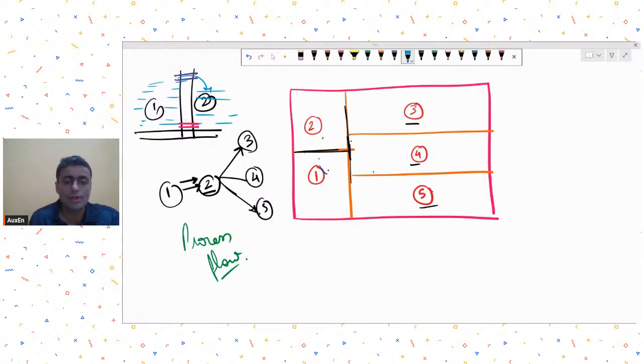So how do you need to understand this? When tank 1 is going to be filled, the water pressure will act like this. Do you understand? Now you may need to make one load case. Let's call it load case W1, where you will apply the water pressures on this tank first.